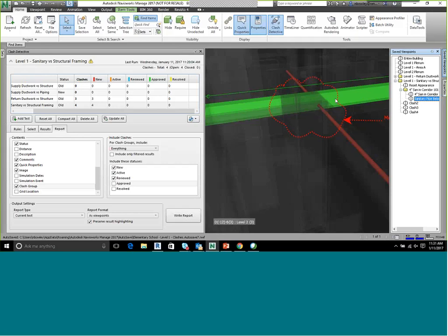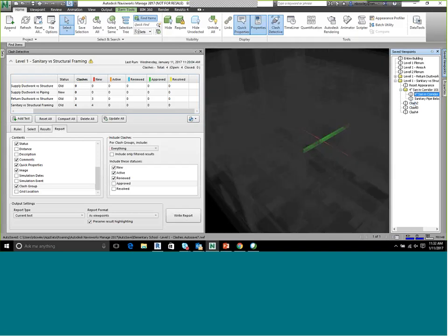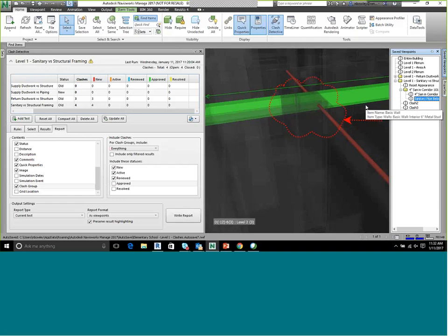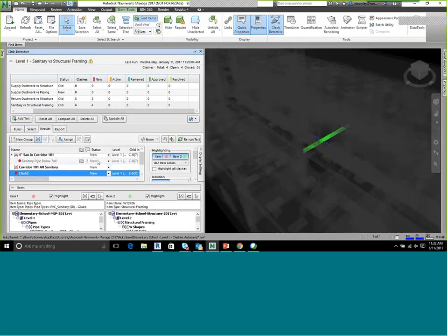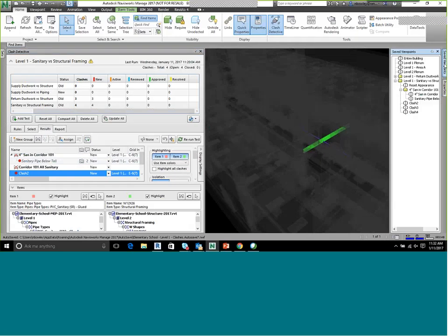Again, I don't like to mark up in save viewpoints. So remember my clouding and doing all my text notes? I don't want to do it in save viewpoints because next time I run my clash report and export my viewports, I'm going to have to remark all these views up versus having all those markups saved in the view, in the clash report view. Next time I export it, I'll have those same comments again. I don't have to remark it up.